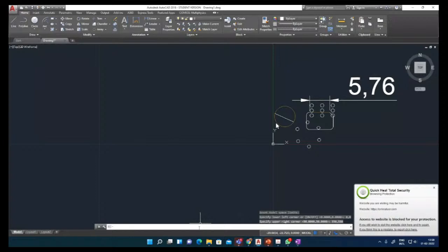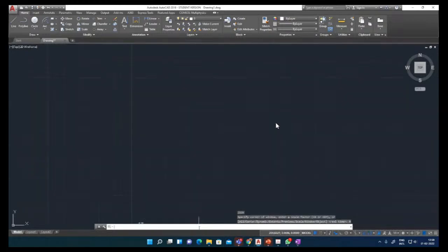Then you can use the zoom command. There are different types of zoom. I want to zoom to all the area, so I can type A, and then you can see. Now you can see this coordinate point here is changing. It is not exactly the working area you gave; it will be more than that, because I'm trying to zoom all.